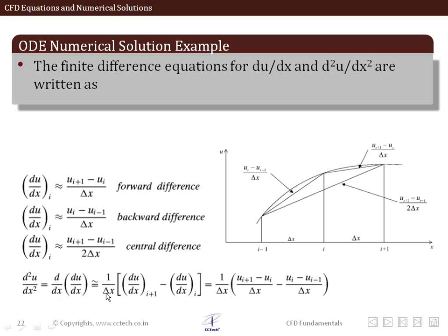That's a numerical approach, and using the first order term of the Taylor series expansion, we have an equation of this form. Now what this shows is that we have truncated some terms. This is where the truncation error comes in. We have not included the second order or higher order terms. We are just assuming d by dx as a difference equation, as you can see here. So that's where the truncation comes into the picture. We'll be speaking more about what this truncation error is in the subsequent slides. But you can remember this, that CFD involves truncation errors, round off errors, and modeling errors. And this truncation error is something which comes up here.